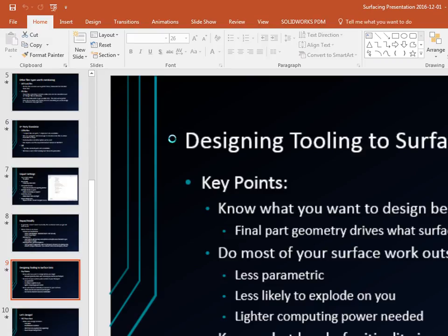even though they're touching each other, I just want those two faces just as an example. I'm going to open up that parasolid and we'll see that those are two separate bodies at this point, which usually you want them actually knit together. Now you could just go through and knit them together. That would work, but it's an extra step. So you may as well just save it as an IGES.